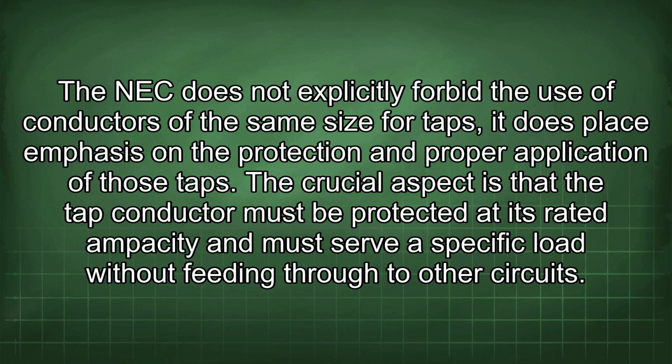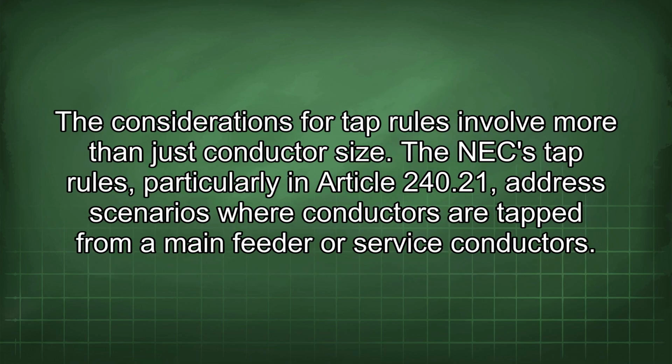It does place emphasis on the protection and proper application of those taps. The crucial aspect is that the tap conductor must be protected at its rated ampacity and must serve a specific load without feeding through to other circuits. The considerations for tap rules involve more than just conductor size.